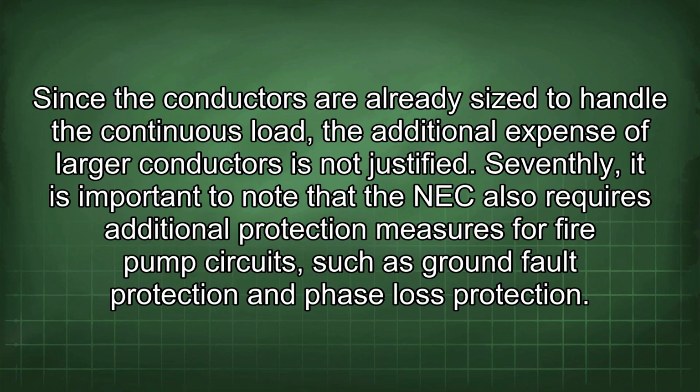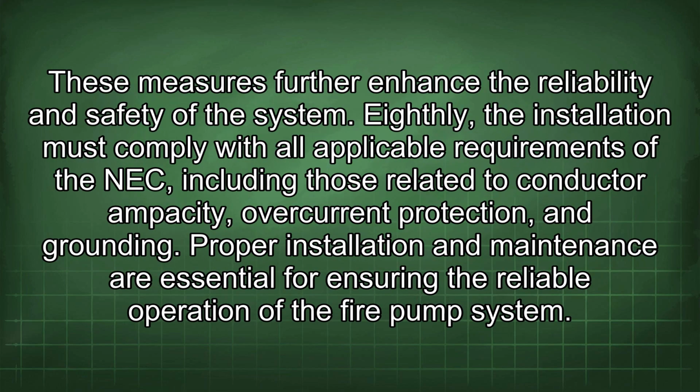Seventhly, it is important to note that the NEC also requires additional protection measures for fire pump circuits, such as ground fault protection and phase loss protection. These measures further enhance the reliability and safety of the system. Eighthly, the installation must comply with all applicable requirements of the NEC, including those related to conductor ampacity, overcurrent protection, and grounding. Proper installation and maintenance are essential for ensuring the reliable operation of the fire pump system.